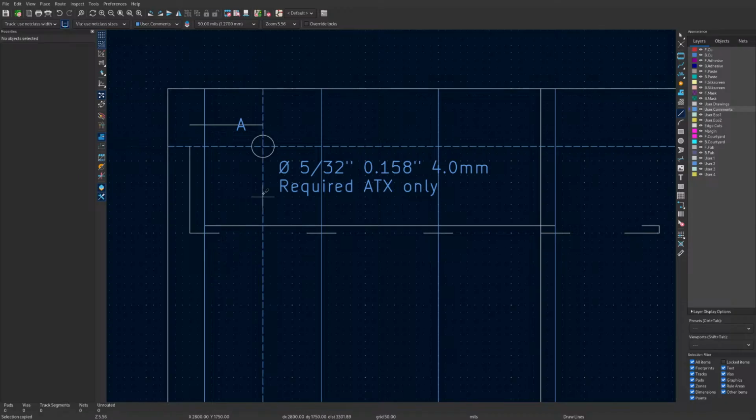Yes, down to the pin 1, and to the left edge, I think I misread. Pin 1 is 0.5. I originally thought that was the edge of the board, so now what's the edge of the board is 0.65. 0.65, that is correct.